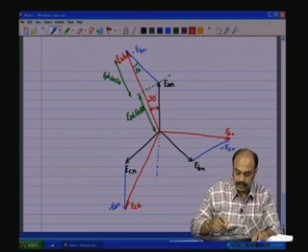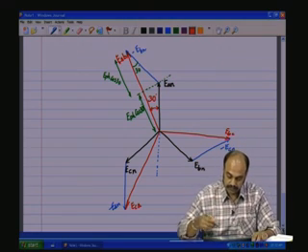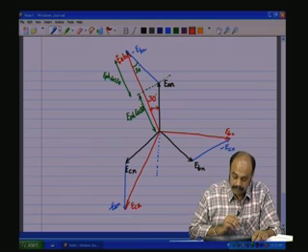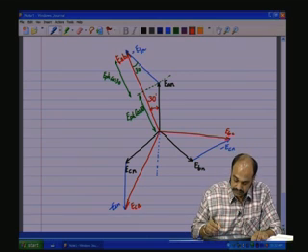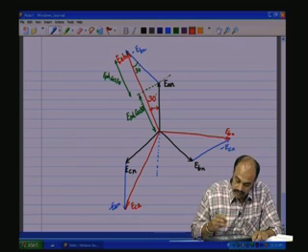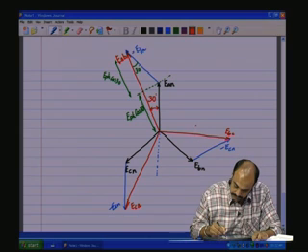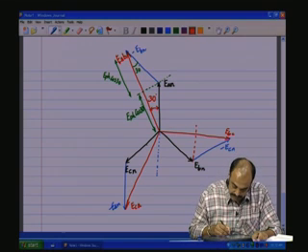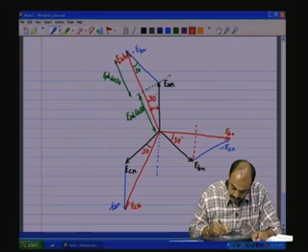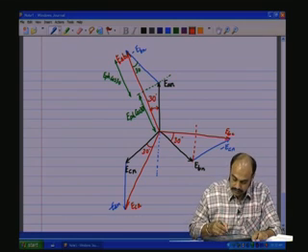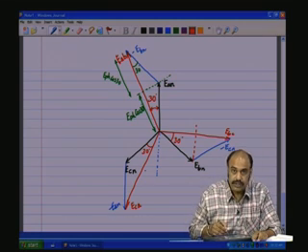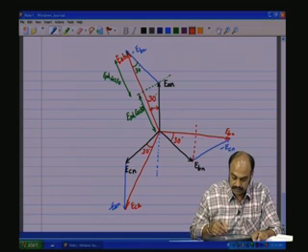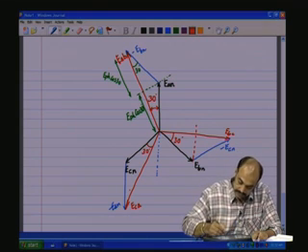So, you see symmetrically all the phases will have a similar type of phasor construct, and in all cases the line voltages are nothing but projections of these two phasor voltages, and in all cases the line voltage is leading the phase voltages by 30 degrees, and therefore, the line voltage here will be twice the projections of the phase voltage, which is again root 3.